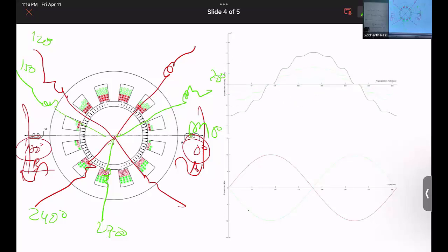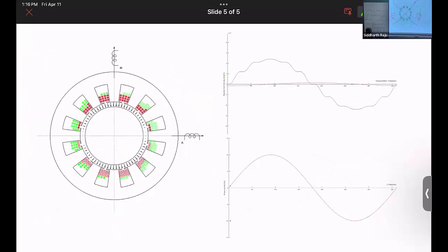But with the second one, where I've drawn it in green, you get the advantage of some torque cancellation, that is, harmonic cancellation. Because the H field we saw is not a pure sine wave. It had those step values. And when you do an FFT, you can reduce it into harmonic components. And when you have these asymmetric configurations, you can cancel out some of those harmonic components, right? So that's the advantage of doing that, okay?